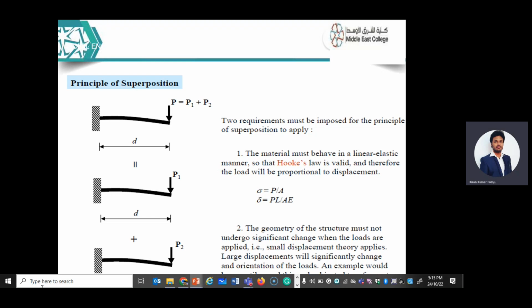If he runs slow, he will get it very slow. So stress is directly proportional to strain within the elastic limit, which is called Hooke's law. That is applicable in today's experiment, which is called the tensile test. In this experiment, when we are applying some load, some stress, the strain is also similar. If you give very little stress, you get little strain, until the elastic limit.